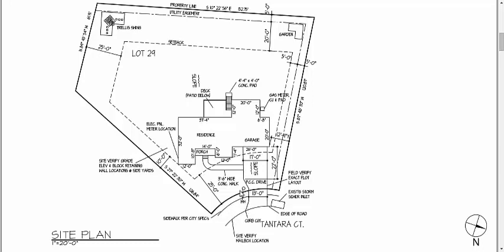MH, we got a manhole, and that kind of stinks, to be honest with you. Right in the middle of your lot, you got this curve here, you got that manhole to deal with. And it caused some problems for this house, as you can see, because what did they have to do to their driveway? So the driveway comes down like this, goes right down here straight, and if it would keep going straight, you'd run into your manhole. Well, that's not good. So you got to take that driveway and you got to kind of veer it in a little bit like this to go around that. So you actually took your 17-foot driveway up here and you condensed it down to 13 feet here. That's not very wide and kind of a hassle, to be honest.